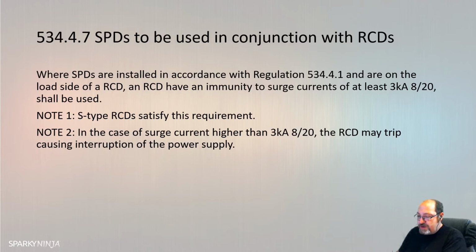I'm trying not to go into too much depth, to be honest, with the SPDs, because it's probably going to require a dedicated video to understand some of this. But similar to chapter 44, where we had the impulse withstand voltages, we've got some data here on the configuration and the minimum required Uc of the SPD depending on the supply system's configuration, and impulse discharge is mentioned there with supply systems.